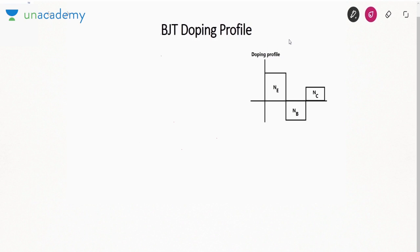Now if you see here, suppose it is P, N and P. Due to P, we have shown it to be positive. Due to N, we have shown it to be negative. Due to P, again we have shown it to be positive. Okay. Now if you see here, NE, this height is maximum among NB and NC. So this height is more than NB, and again this height is more than NC. So the doping is something like this, that doping in emitter is more than base, which is more than collector.